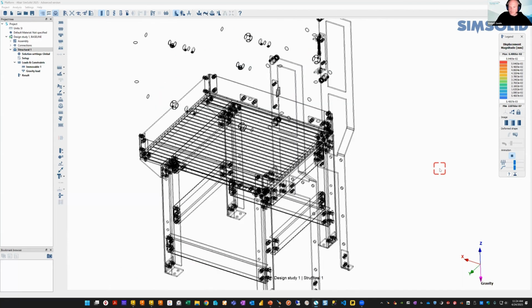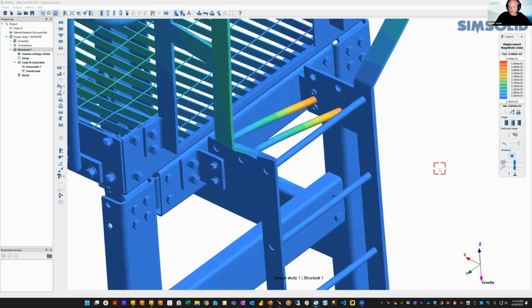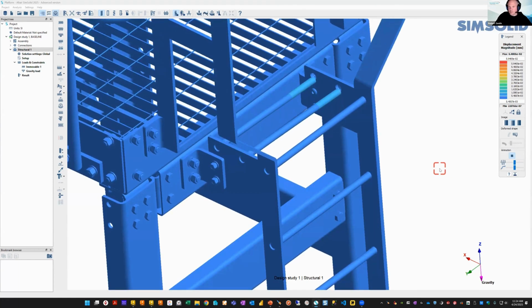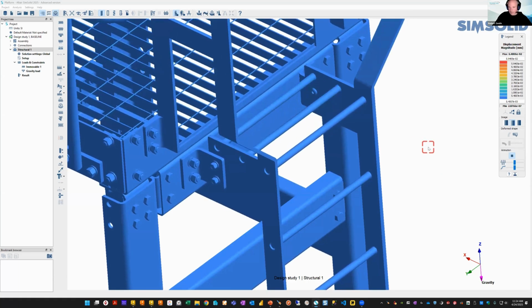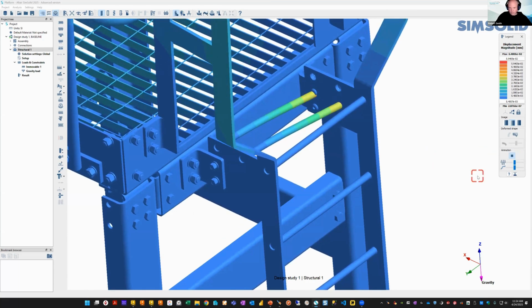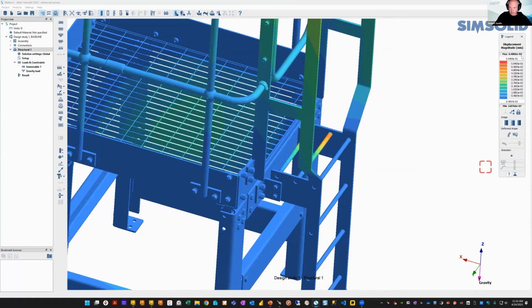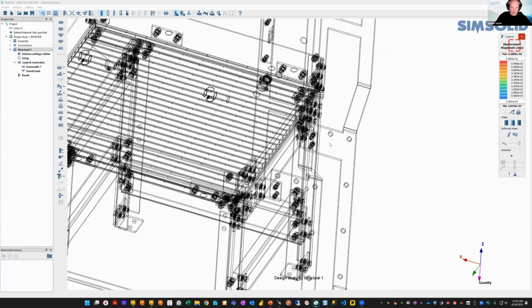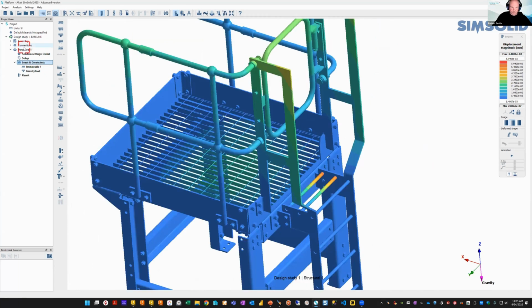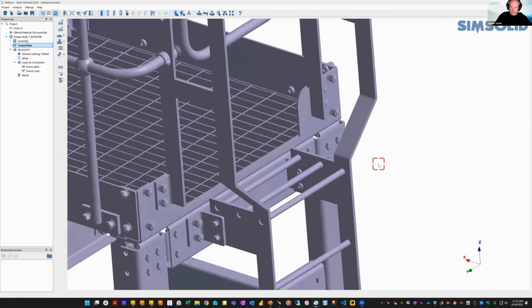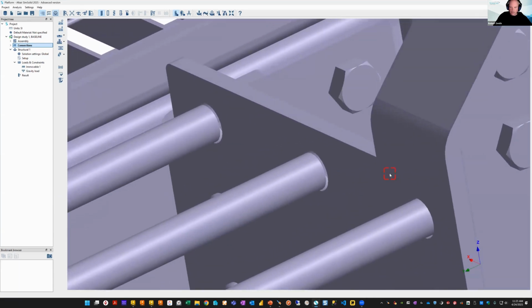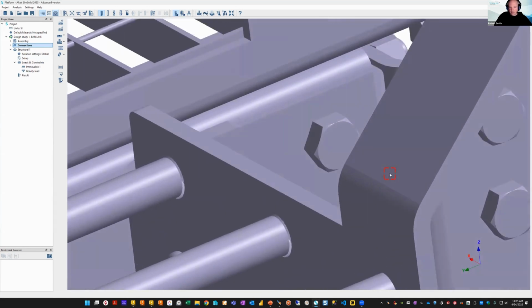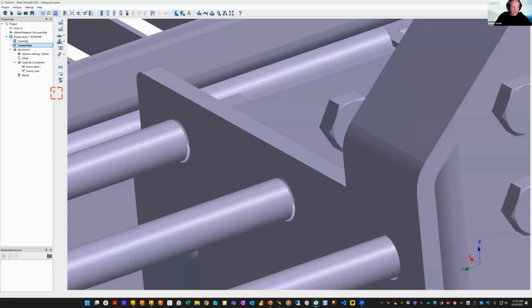So you may notice, if you've got a keen eye, that I've missed something here, and that was intentional. That little gap was made big enough so that we intentionally have something to fix there. Because I'd like to show you some other stuff like the ability to weld parts together, for example. So let's do that. I'll stop my animation. We'll go back to the setup. See, the gap is big enough there that my automatic contact didn't catch it. I could have, with a larger setting in the automatic contact, caught that, but that wasn't my point.